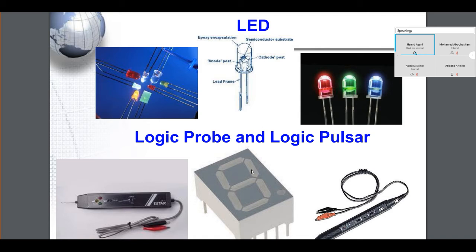You have to be familiar with using a data sheet for a 7 segment, for an LED, for a transistor, for the TTL family, I mean the chips. You have to look for data sheets. The manufacturer of each one of these will give you how you can connect each leg or each terminal, with names and numbers for each terminal, and you can identify them easily by referring to the data sheet of that component. How can you look for a data sheet on the internet, in Google?